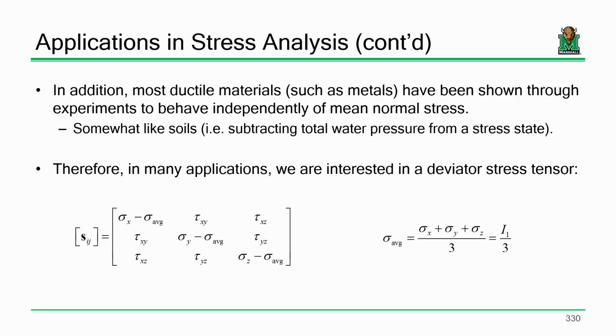In other words, how many of you have ever heard of the Marianas Trench, the deepest point in the ocean on the planet? If I were to take a block of steel and test it here versus testing it down at the bottom of the Marianas Trench, I wouldn't get any difference in its properties, because material properties are really independent of hydrostatic stress.